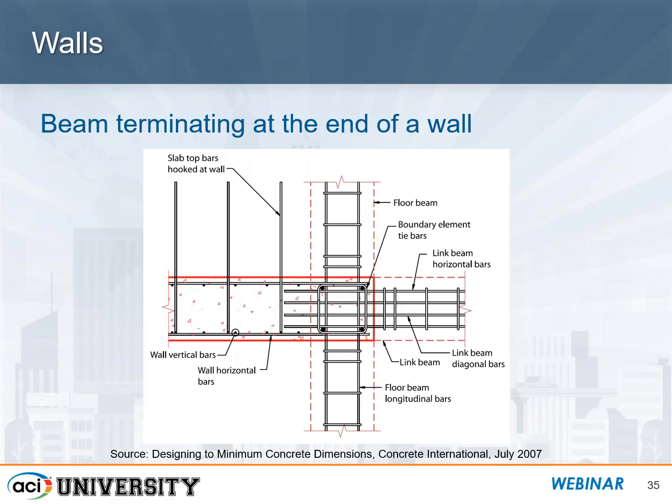Now, for special seismic walls, that's a particular designation where, along with that, comes some very special detailing for the transverse reinforcement. But in general, even if it's just resisting wind, we can concentrate some big bars at the end of the wall to resist the wind forces, and then tie those up to provide some good lateral support. So if we need to do that, we want to make sure we have a thick enough wall in order to be able to put those ties in.